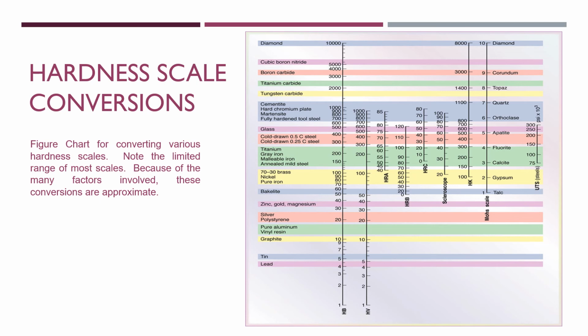If you use HRA, it is 50 HRA or 80 HRB, none of it in HRC, because HRC is for stronger material. That is where we use the conversion table, because not every country accepts every standard; some countries only accept certain standards.